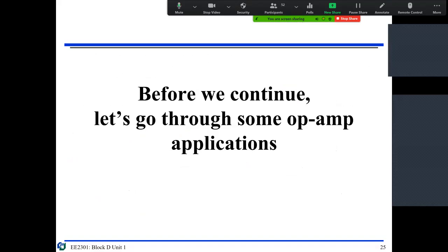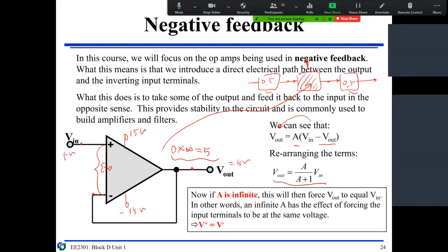So we think about op-amp applications. Right now, we've gone through this and explained it. You can imagine that after you apply this, your input impedance is infinity and your output impedance is 0. So you don't have the impedance matching issue. Sometimes this is also called a buffer stage. I put a buffer stage here so that I don't have to worry about the impedance matching issue.